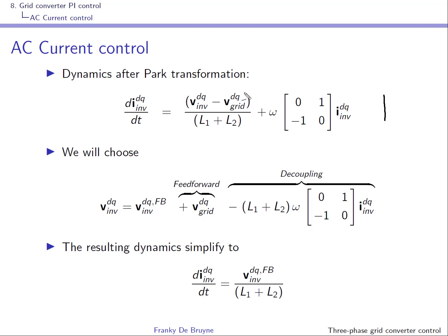This thing here is something that you have to live with. It can be seen as a perturbation. It's the grid voltage, and this is the coupling effect. And this coupling effect makes the control a little bit more complicated. So this is the part where we have to be smart, and this is the part that we can control.